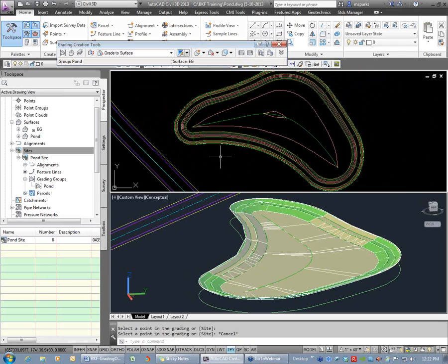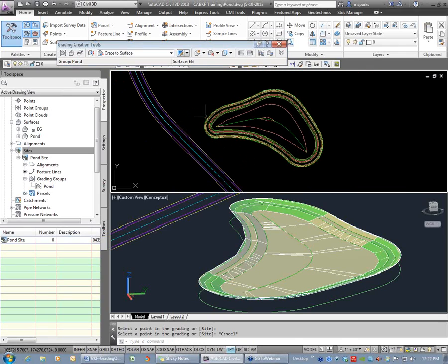Now this time, let's say, for example, I'm close to the road over here, so let's say I want to do like a 2-to-1 slope over here. But over on this side, I want it to kind of maybe, if it overflows, there's some open space, maybe I want to go like, let's say 5-to-1. So I want to go 2-to-1 in this area, but 5-to-1 over here. And then how do I transition between these different slopes? I'm going to walk through that.